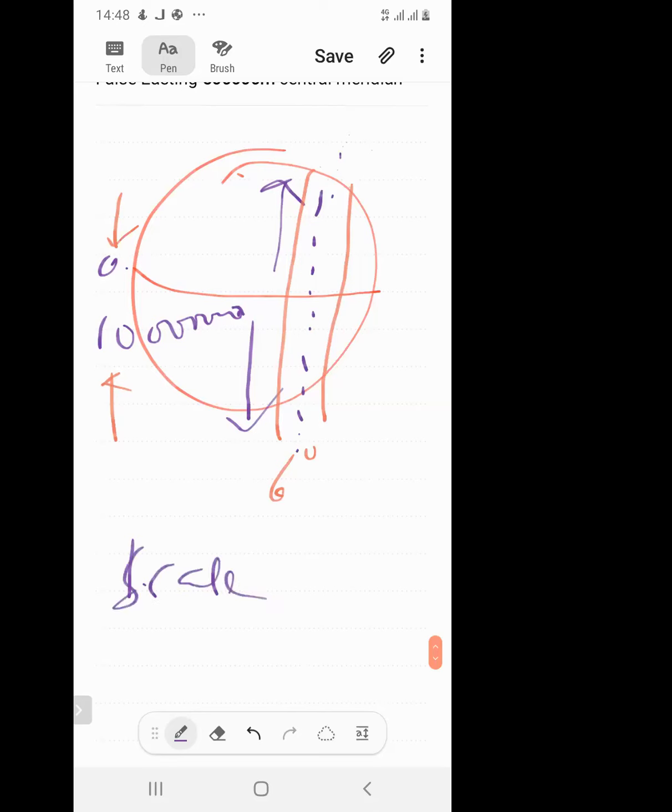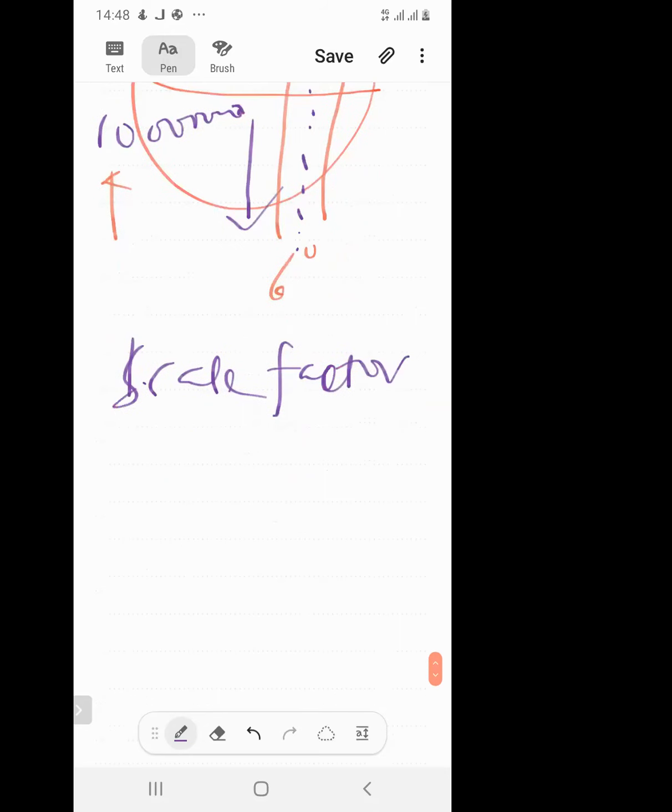Now, if you don't know what scale factor is, then you need to go and review your math book from class 5. Okay, it's in there. A scale factor of 1 means there's no transformation, there's no change, and I prefer that. After the earth has been projected, if a scale factor of 1 is observed, it means the object didn't change. If it's a long road, maybe an airport runway, a very long one, it didn't change. So that's what I want.